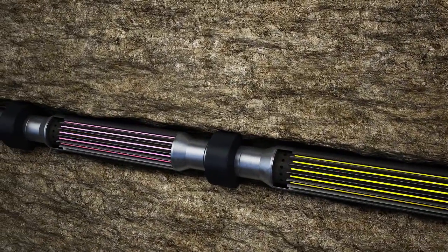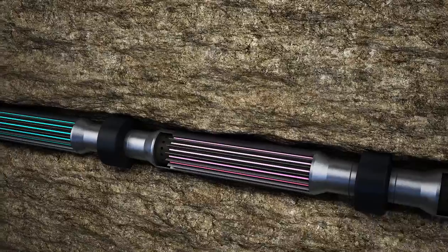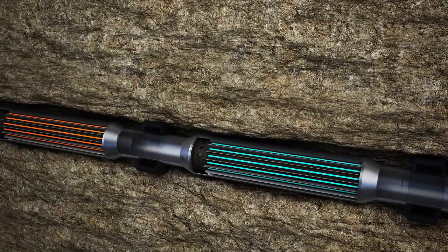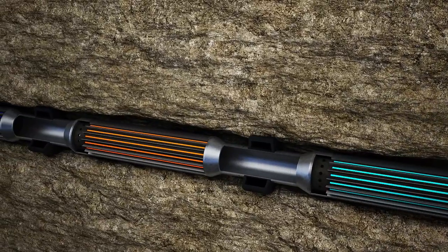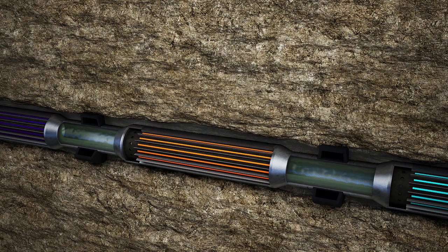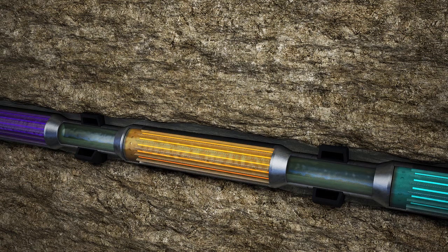In a single flow stream, RESMAN has the capability to deploy over 50 unique chemical signatures for oil inflow detection and 50 unique chemical signatures for water inflow detection. When the well is static, the chemical released from the rods accumulates around its vicinity, thereby creating a high concentration of the chemical tracer in the surrounding oil.